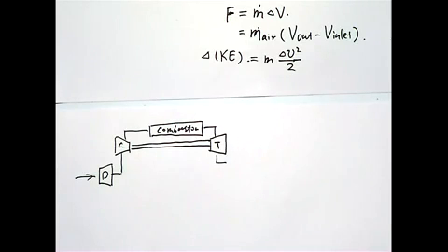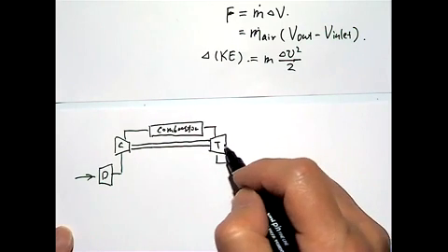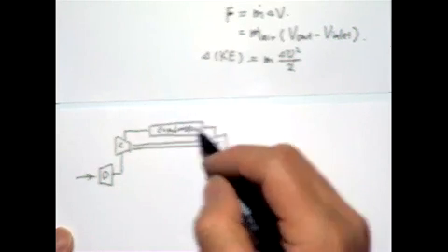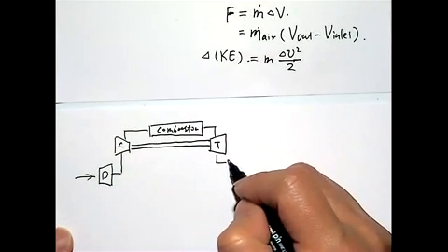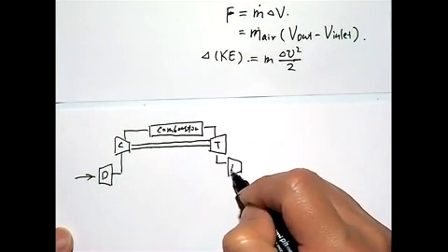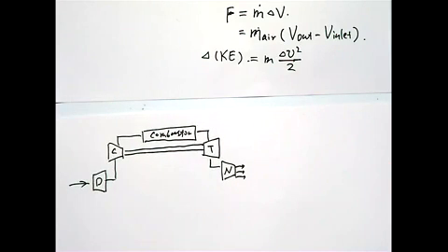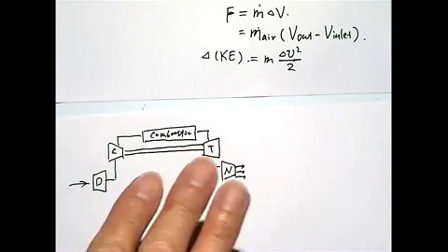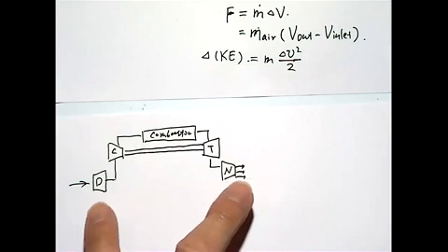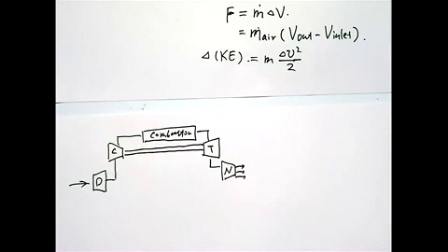The function of the turbine is basically to drive the compressor, essentially. This turbine does not output useful work. So the unused thermal energy from this process then goes through a nozzle to produce the thrust. This basic layout is similar to the Brayton cycle, except that we have two components, the diffuser and the nozzle. It does not always have a diffuser, but the nozzle is always there.